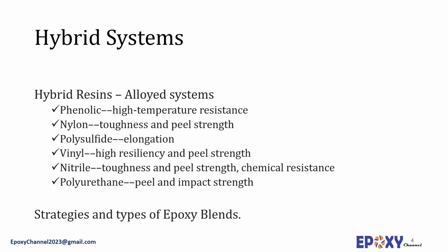Epoxy hybrid adhesives are often used as film, supported and unsupported, or tape because of the ease with which formulated systems can be dissolved into a solvent and applied to a carrier or deposited as a freestanding film. Some systems, notably epoxy-urethanes and epoxy polysulfides, can be employed as a liquid or paste formulation because of the low viscosity characteristics of the components.